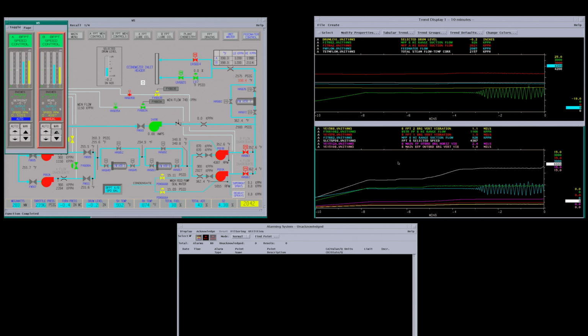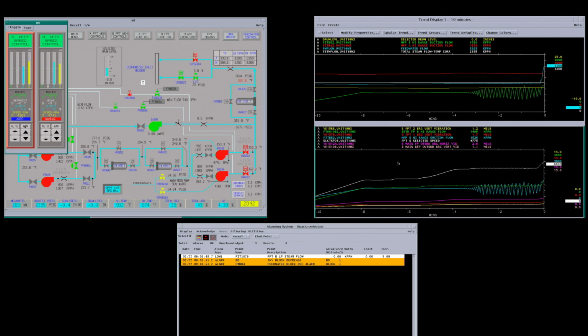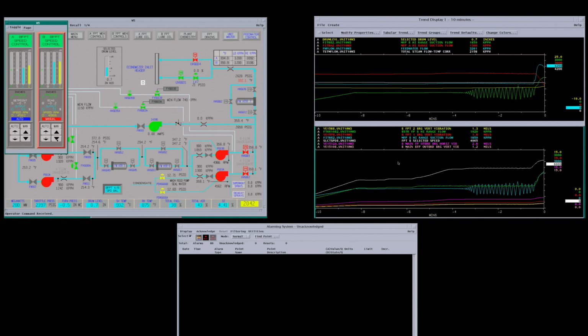Recirc valves will close. We'll get this running, then we'll bring the other pump down, and we'll throw them back into auto. You don't ever want to get to the point where both these things are running in manual. Just have your feed pumps and stuff in automatic. I'm going to drive him down a little lower, kind of line up the speeds on them so they don't jump too much.